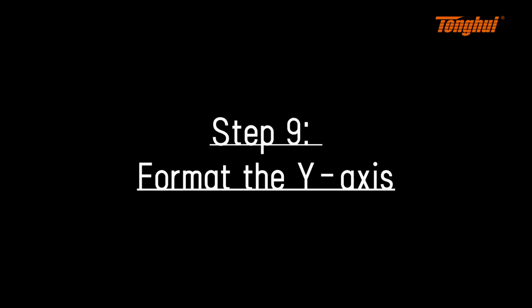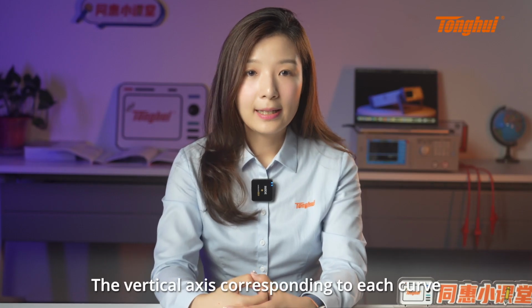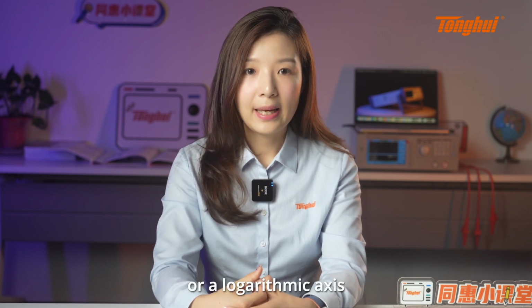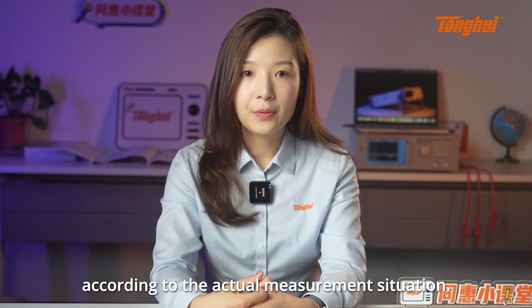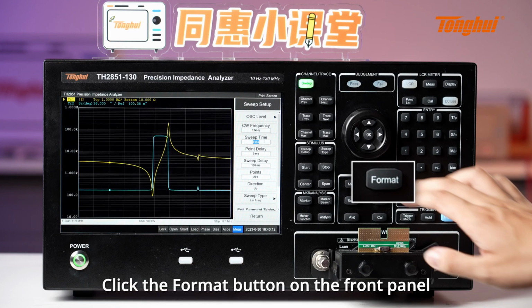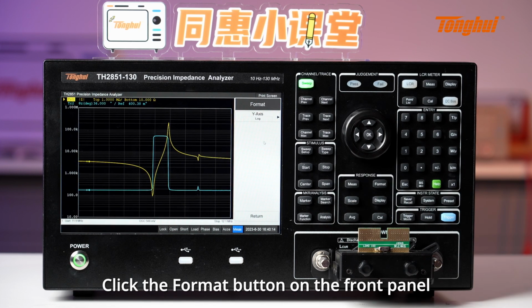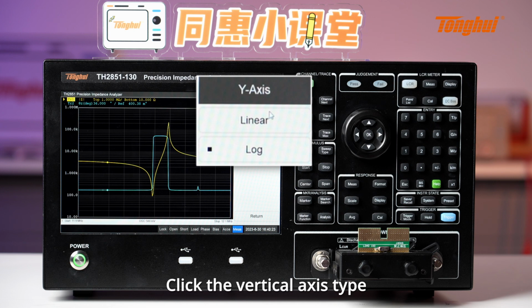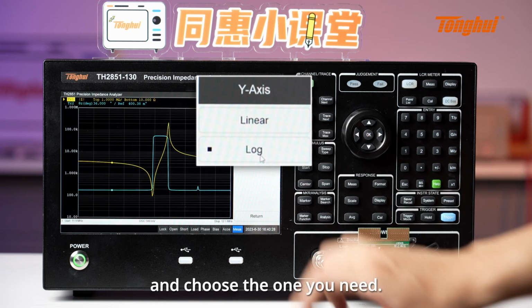Step 9. Format the y-axis. The vertical axis corresponding to each curve can be set as a linear axis or logarithmic axis according to the actual measurement situation. The steps are as follows. Click the Format button on the front panel to enter the Ordinate Format menu. Click the Vertical Axis type to enter the Vertical Axis type menu and choose the one you need.